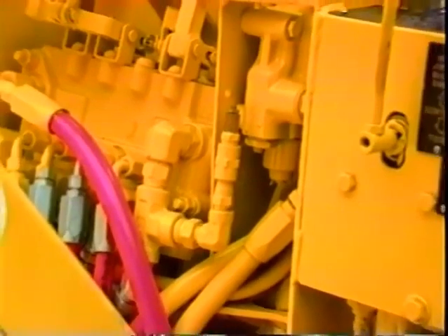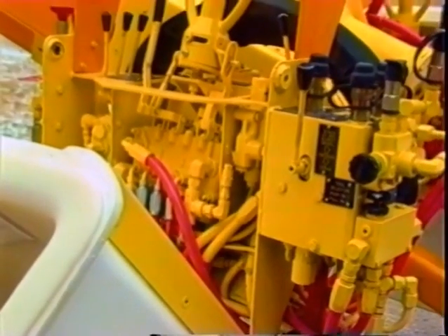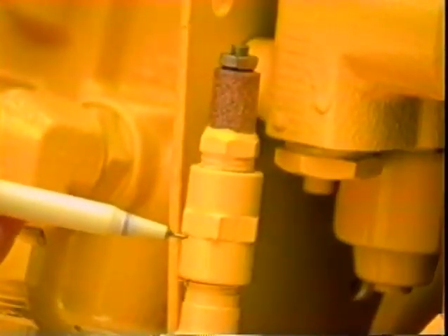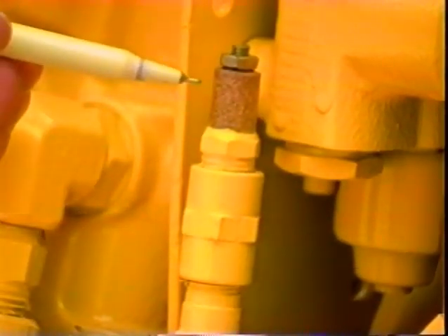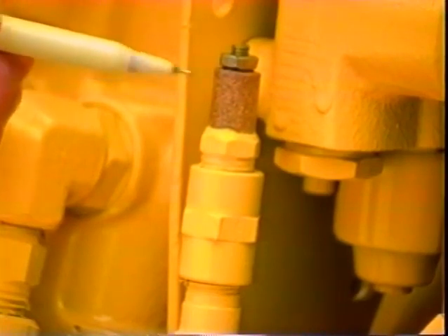To prevent this from happening, the upper boom is equipped with one or more anti-vacuum relief valves. If the pressure in a hose drops below atmospheric, its valve opens, allowing air into the line. The breather filter at the end of the valve must be changed at regularly scheduled intervals.